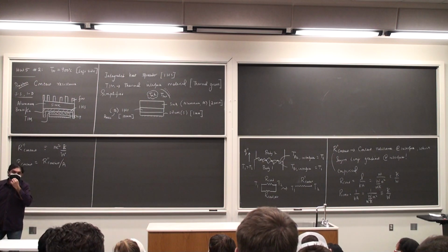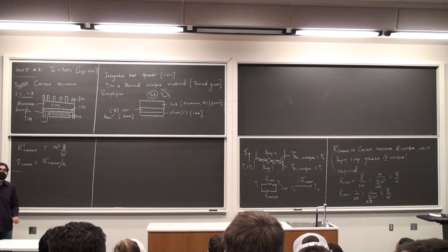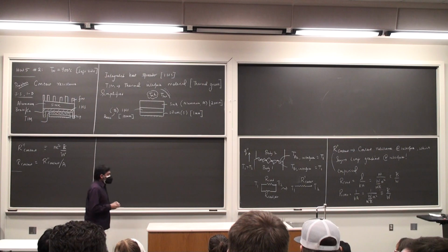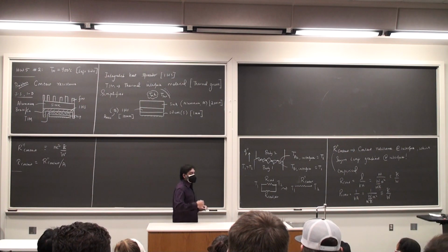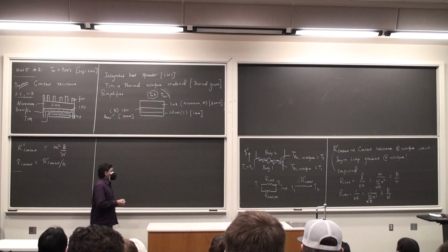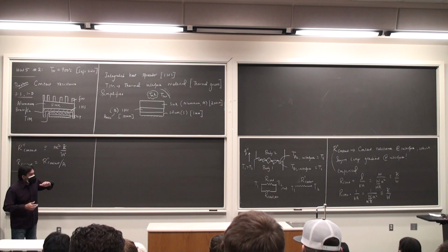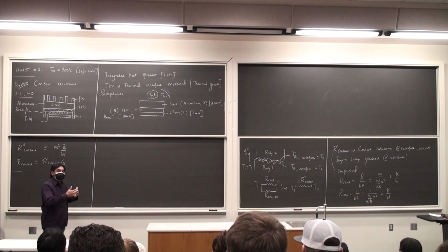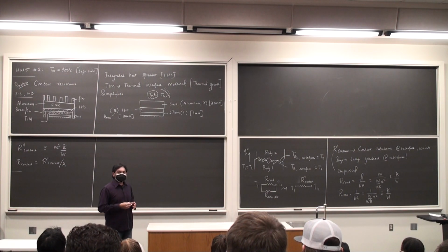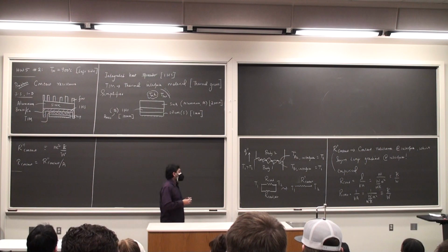Yes? How does the thermal conductivity of the thermal paste compare to the thermal conductivity of the metals used in the heat sink and the? The thermal conductivity of the paste is going to be much lower than that of the metals. And so typically you see that if you're applying a paste, it's a semi-solid or a fluid, so their thermal conductivities are going to be lower than that of the actual materials in contact. But it's going to be better than that of air.